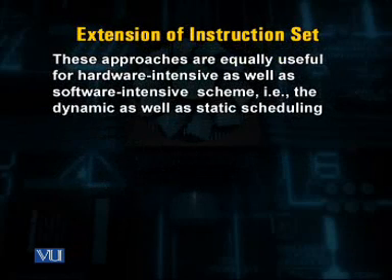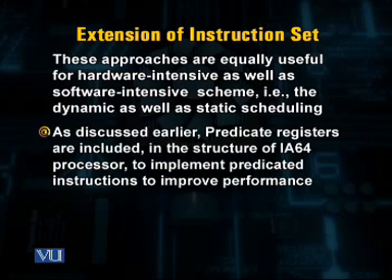These approaches are equally useful for hardware-intensive as well as the software-intensive schemes, that is, both for the dynamic scheduling as well as the static scheduling. Now, as we discussed earlier, predicate registers are included in the structure of the IA64 processor.